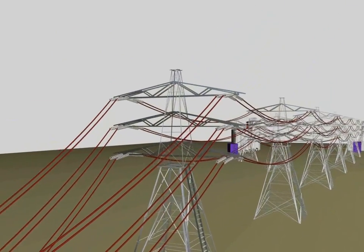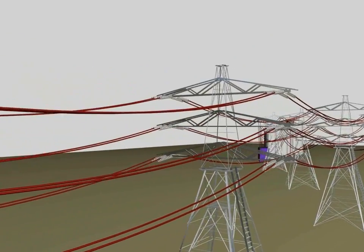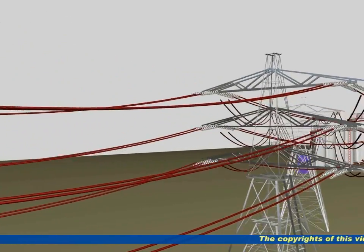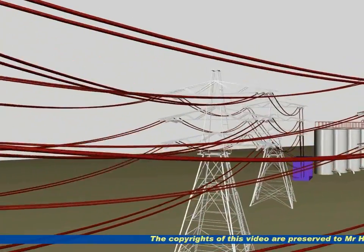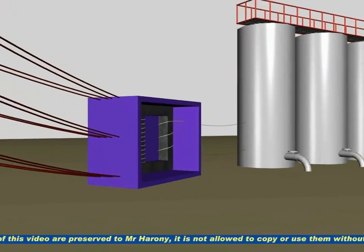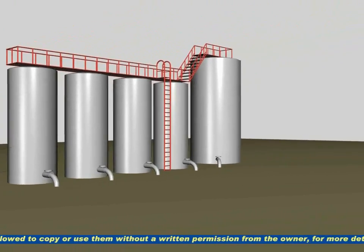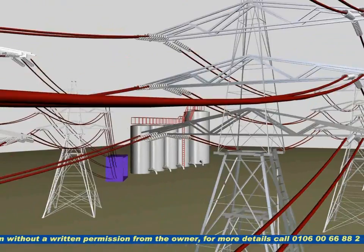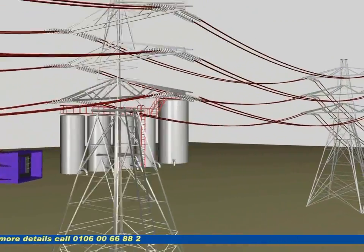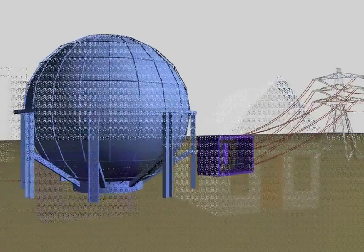This is to minimize the heating up of the wires and hence minimize the energy and power loss due to the resistance of the cables. Before factories and industrial areas, there must be a step-down transformer. This is to reduce the voltage and increase the current to values that are suitable for industrial uses. Also in populated areas, a step-down transformer is needed to reduce the voltage and increase the current to suitable values for home use.